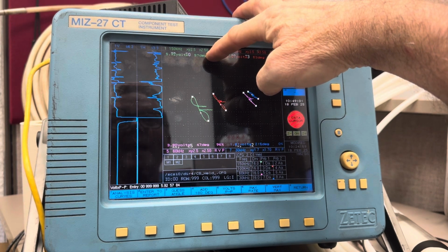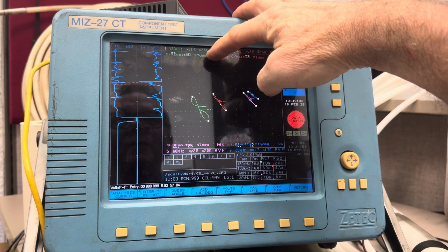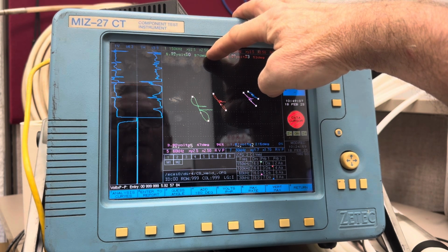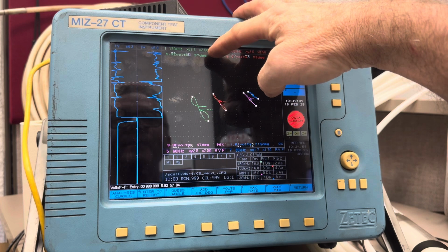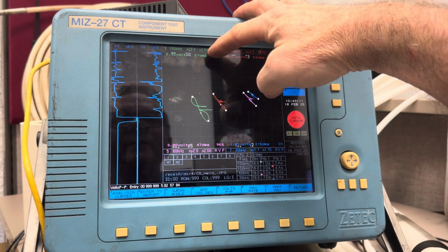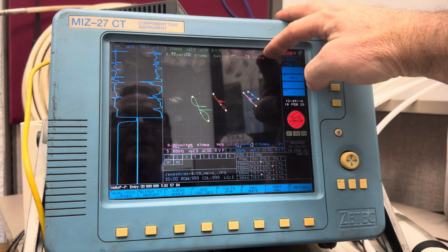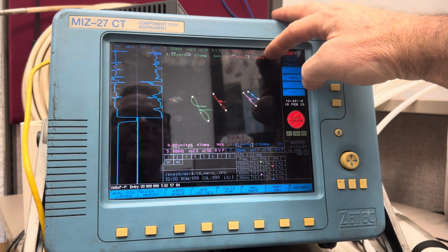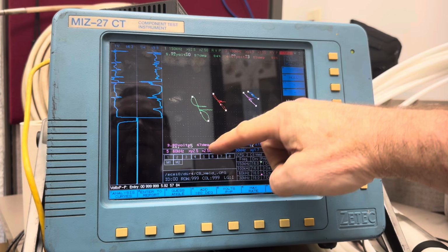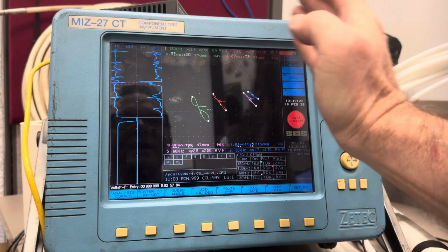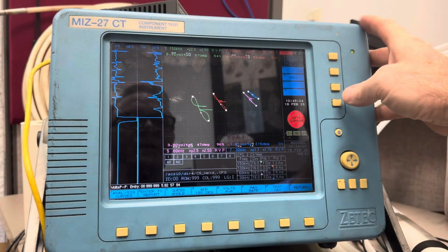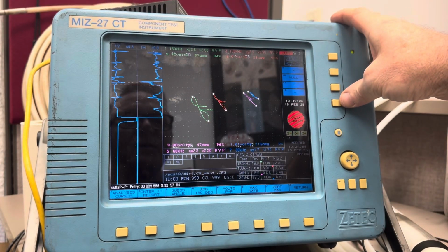Now, without moving my hand, I said that OD flaws rotate counterclockwise as you decrease the test frequency. So when I move over to the red channel there, that's going to be 100 kilohertz. It should be less than 57 degrees. Voila, it's 53 degrees. Now when we go down to the purple data, it's going to be less than 53, 47 degrees. See how that's rotating counterclockwise with decreasing frequency? That is how you do phase analysis.